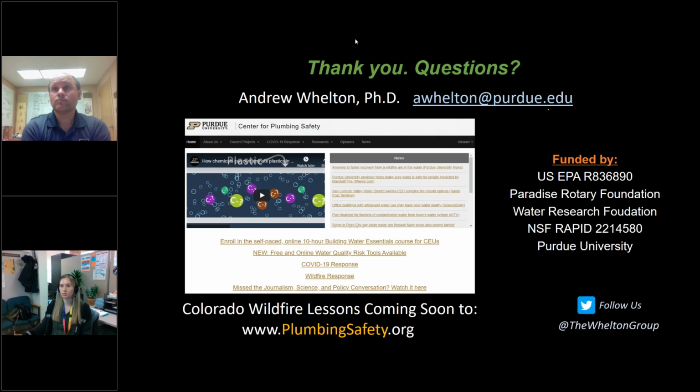Okay, and then the last question here, could you expand on the thought that boil water advisories could be obsolete? Yes. So a boil water advisory is what we think about in terms of bacteria. So boiling it should kill the organism and inactivate it. And that is something that we've been very comfortable with doing for the last 100 years. Main breaks, pipe breaks, didn't disinfect correctly situations, boil the water. And so we still could potentially have microbial issues in depressurized water systems. But we know that chemical contamination can also be present.